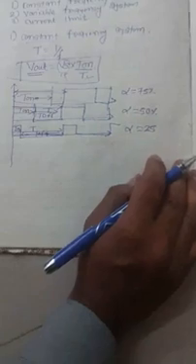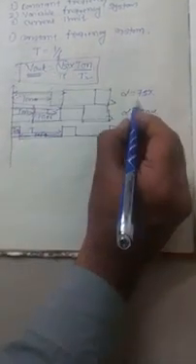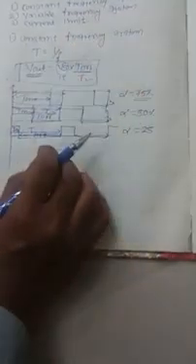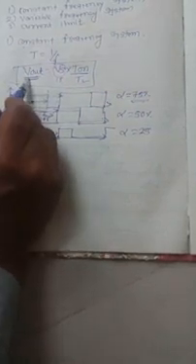In the output voltage equation, the time T is constant, that means frequency is constant, and due to the change of T on time the DC voltage is controlled in the buck converter. For example, with a 75% duty cycle, T on time is 75% and T off time 25%, so the output voltage is 75% of the input voltage.